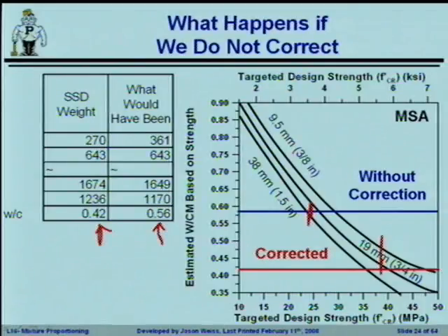One of the ways that we're going to actually make sure that our material is as designed is we're going to do things like a yield test, where we're actually going to weigh a cubic foot of the concrete when it comes out. And we're going to make sure it weighs what it's supposed to. If it doesn't weigh what it's supposed to, that means that there's some adjustment that's been taking place throughout the process. As I mentioned, I believe it was about 2 classes ago, you could use unit weight to track air.